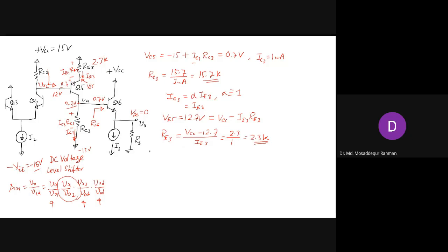That's the gain for the third stage. We can write it as A3, that is V01 divided by V02. It is the collector resistance over the emitter resistance with a minus sign. This common emitter gain is always negative. So RC, the resistance in the collector. What's the resistance in the collector now, right?